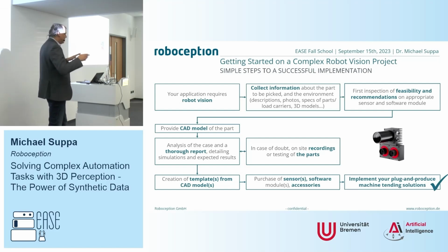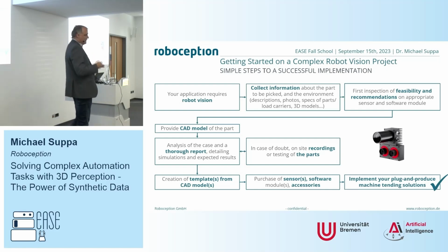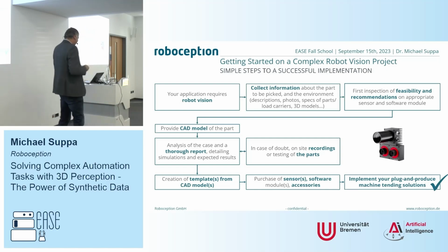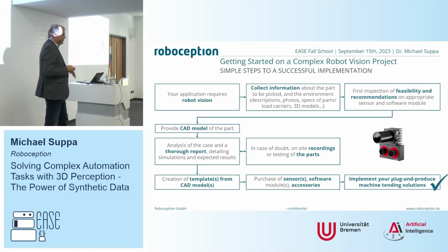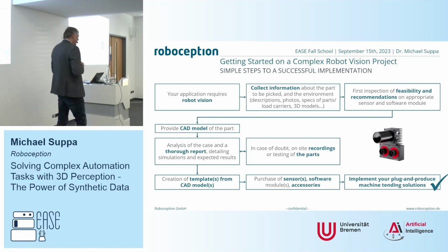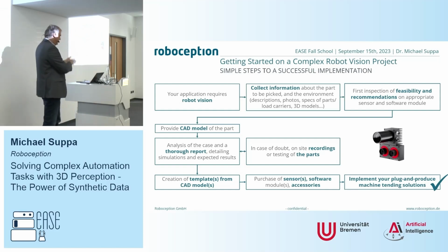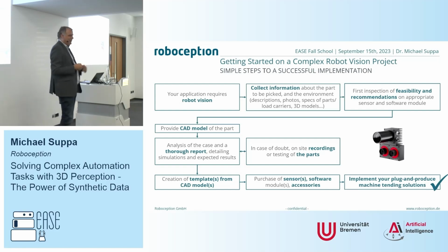So you need to consult left and right on the application, on the gripper, and so on, because usually people say, if they come from mechanical fixtures, sub-millimeter accuracy is no problem in grasping. Now try to do this with a camera. So sub-millimeter accuracy in the pose, I doubt that anyone of you would offer that. So you have to talk to the people that you may have to change something here, because I cannot give you microns, right? So you have to be a little bit tolerant on some parts.